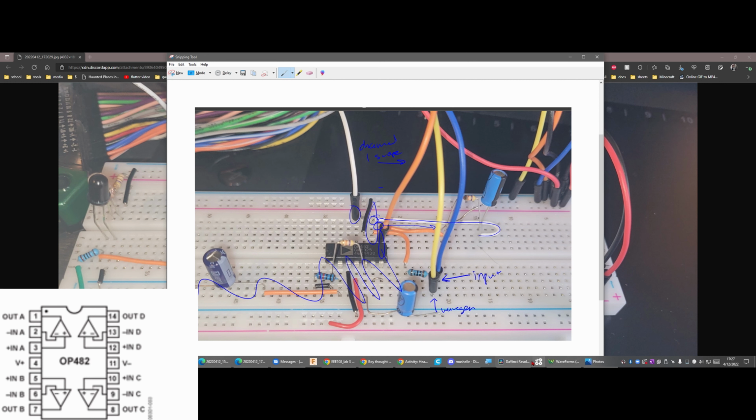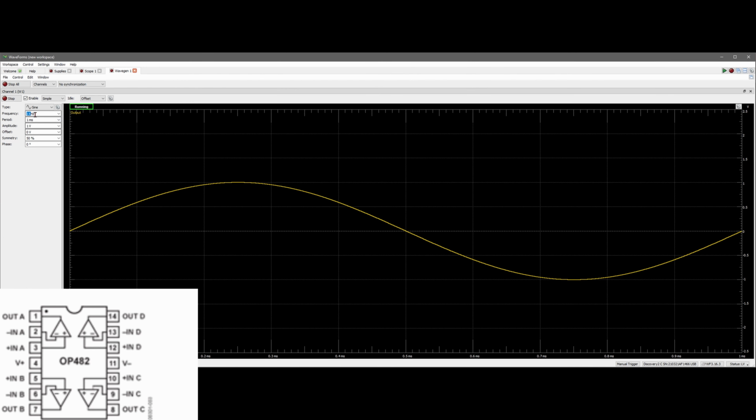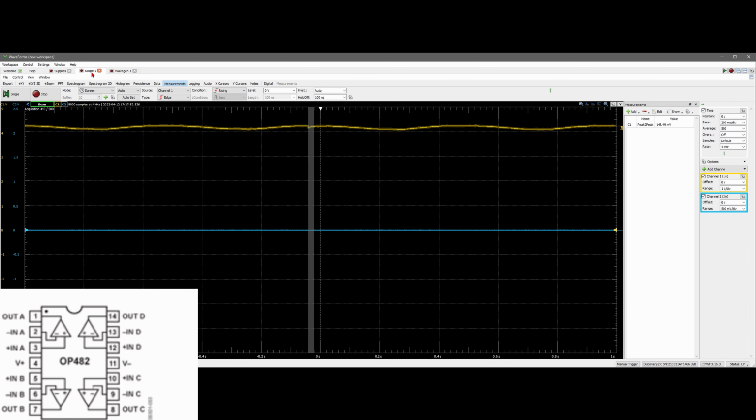So with that known, we can pull up our waveform. We're going to be left with the basic default settings. We're going to change this to 2 Hertz. We want our amplitude to be small, so we'll do 500 microvolts, and then our offset, we'll just have it at 0 volts. So if we go to our scope, we can see that everything is not okay. So we want to have a solid input right here at 0. That's totally fine. That's for our input.